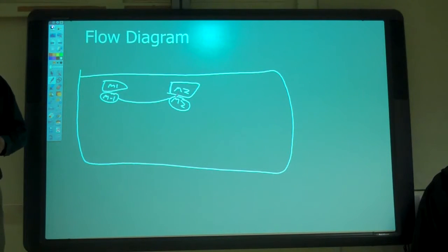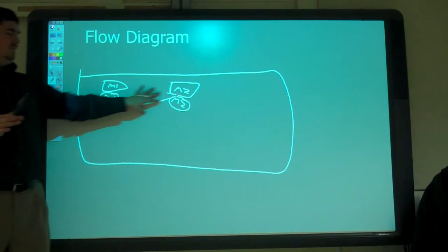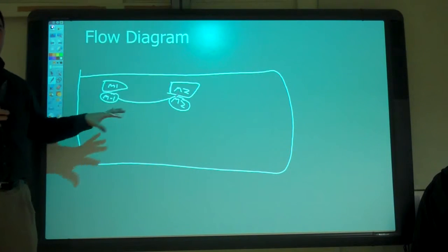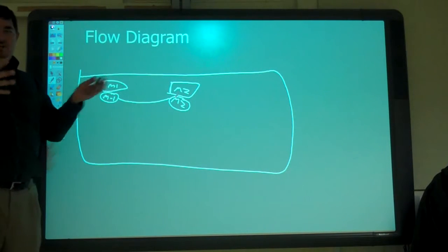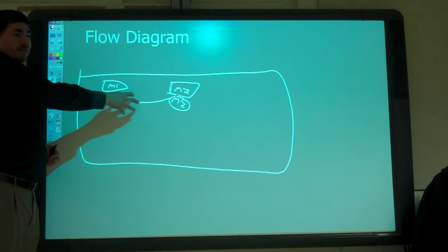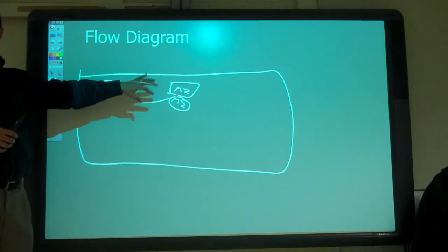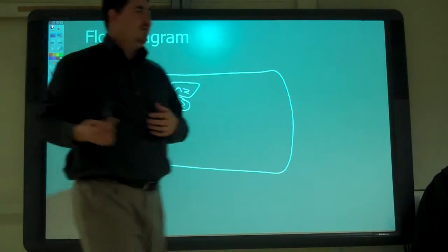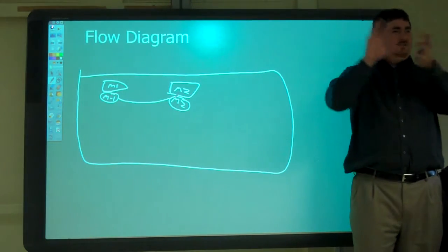That's part of how the shop is laid out. If they're making the same kind of thing, they'll usually group things to make it easier, whether it's all the mills together, or machine centers where you've got a mill, a lathe and a bandsaw right next to each other, so you can go from the bandsaw to the mill to the lathe and keep it all real close. It depends on what type of product they're making. Do they want all of the same type of machining together, or different clusters?